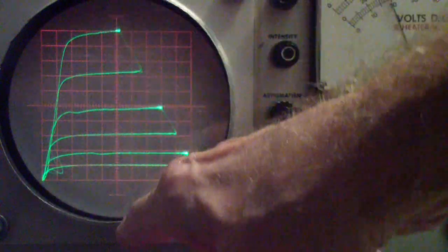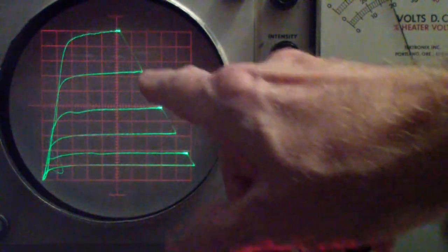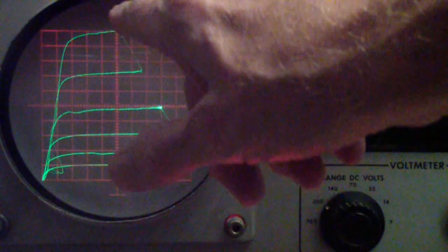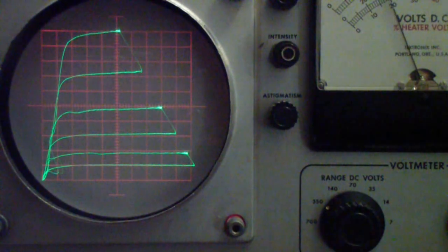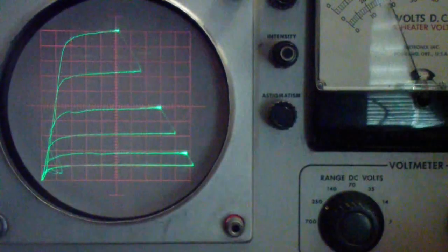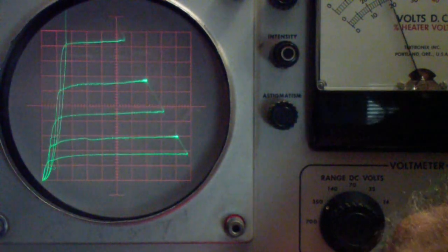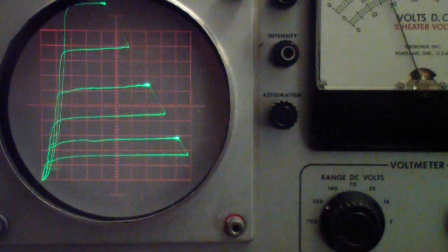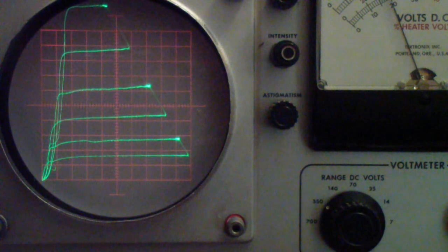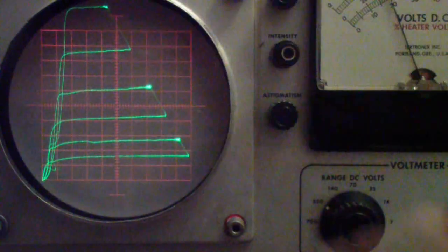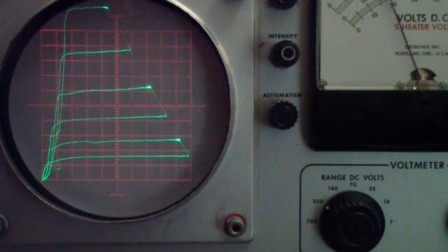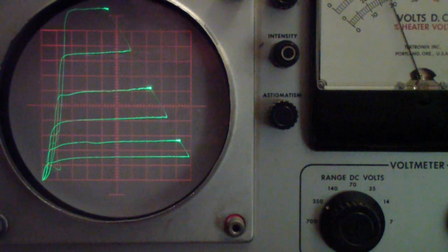The 6U8 triode section, which is a 2-section tube, was the oscillator, and then this would be the power amplifier to drive the yoke. And obviously the 6GH8, which was a later tube developed for the same purpose, has more gain, more transconductance, and so on. So let's take a look at some of those measurements, and that'll give us a little bit of context.